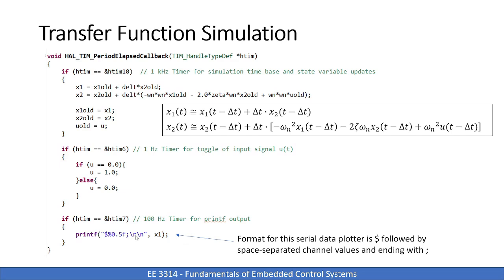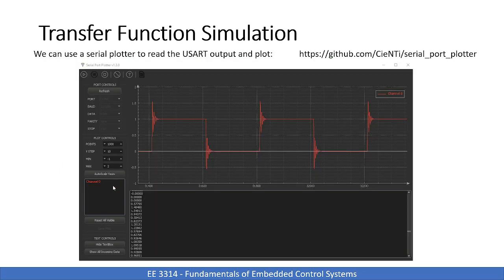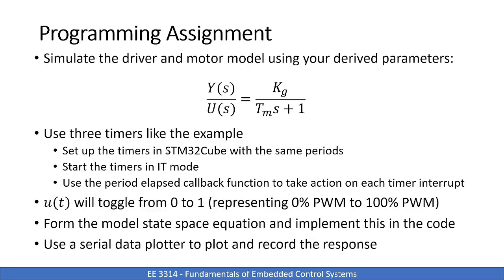So you could do multiple channels if you want, more fidelity, and print more information. This thing will plot multiple channels, and that would look like space separated values horizontally for each one of these printfs. It would interpret each one of those as a different channel. It would plot them up here, channel 0, 1, 2, 3, 4, and so on, as different colors. So it's good for that.